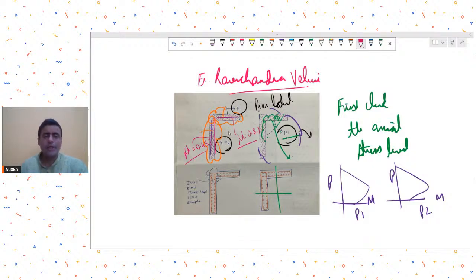That call you can take, but when it comes to pier label assignment, I will always suggest you go with different pier label assignments for different legs. Don't give a common pier label. I am saying this because we will not be able to judge the actual stress levels in every load combination. Better to go with different pier labels.